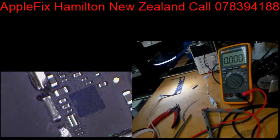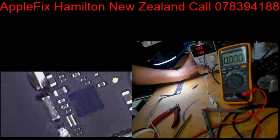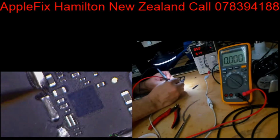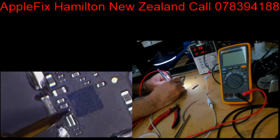So guys, the board is out, and before we remove the U3500, we will check it one more time. So here we are not getting anything, which is the PP3V3_ACC 3 volt line.